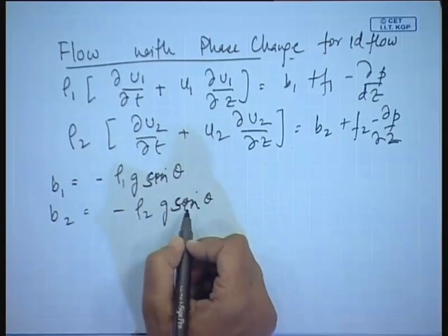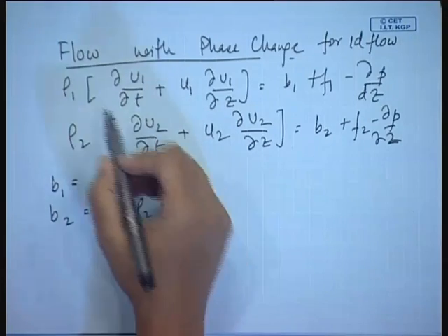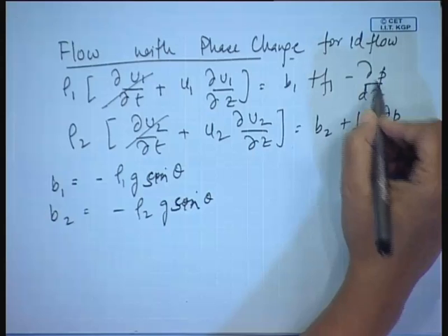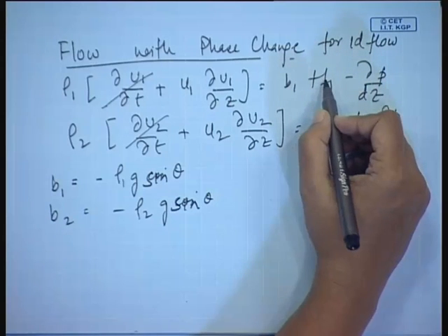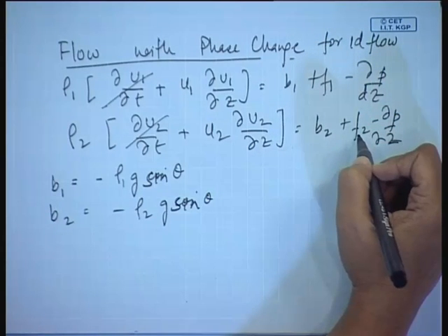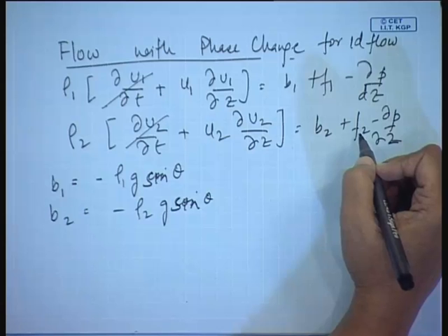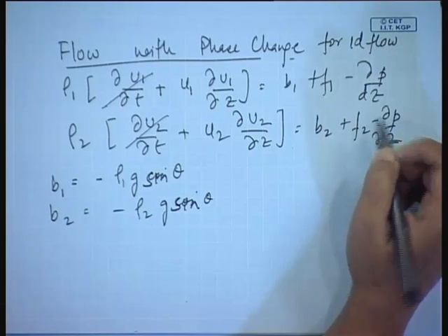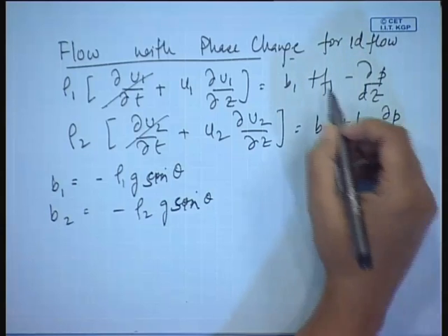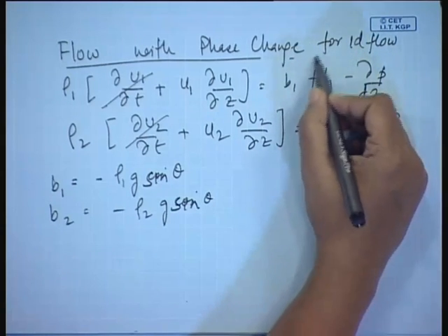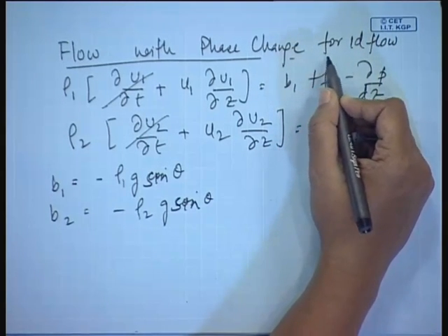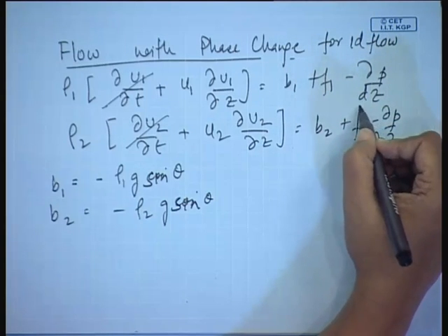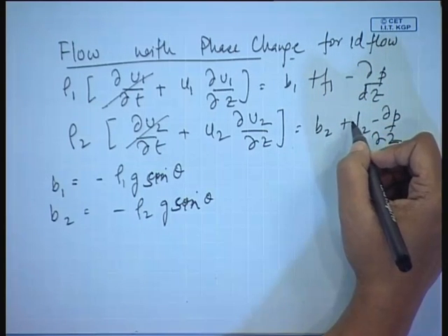So, for steady state condition we find these two terms cancel out. These are the pressure gradient terms, and I had told you F1, F2 are just the leftover forces which are included in order to keep the account straight. Do you remember those things? F1 is the leftover forces per unit volume of component 1, F2 is the leftover forces per unit volume of component 2.